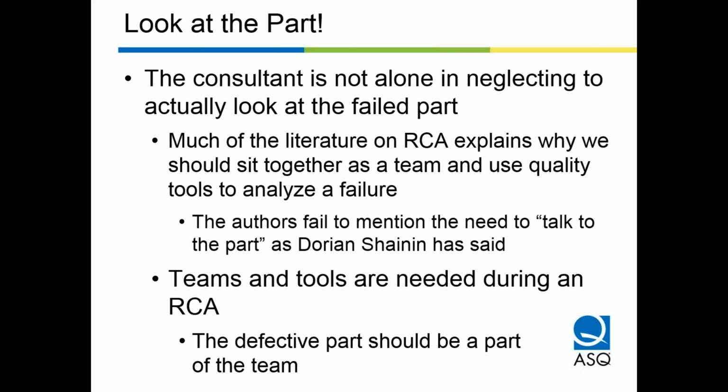This is a sketch, or a recreation of the sketch I drew when discussing the situation with my consultant. Performing a FMEA, that's not wrong. Looking at an FMEA, also not a bad idea. Checking the work instructions. But he did not see the need to look at the defective component. Why? Because we'll do the FMEA. But please look at the drawing there. The area that was breaking had a very thin wall thickness.